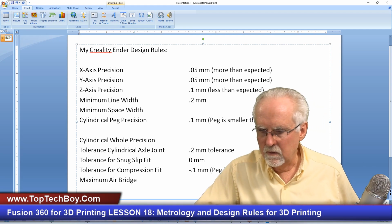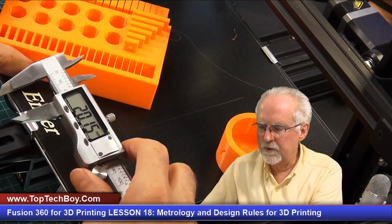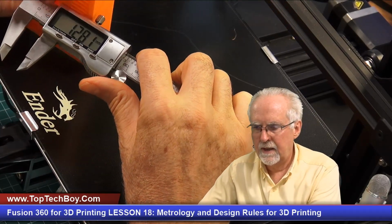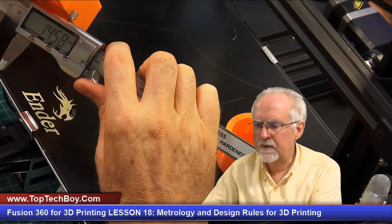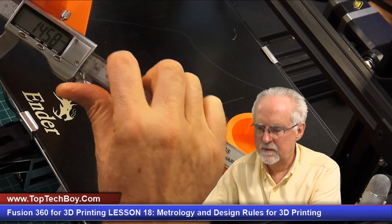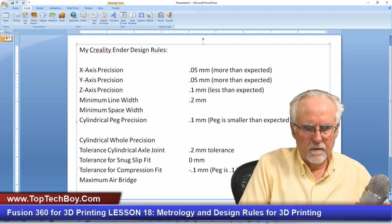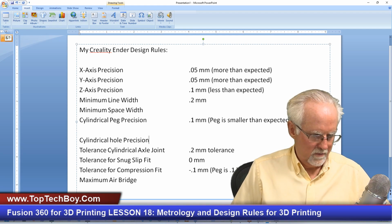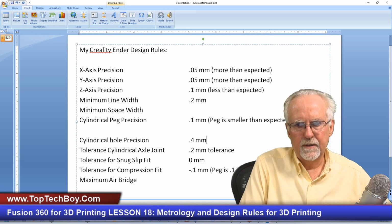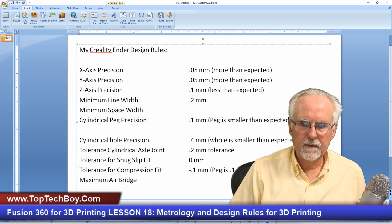Okay, now let's look at the hole, and we are going to come over here. And remember, it was this hole that was supposed to be 15 millimeters. So we'll come in and look at it. What we can see is that the hole is about 14.6. Hole is H-O-L-E, not W-H-O-L-E. So this is 0.4 millimeters. Hole is smaller than expected. Okay, the hole is smaller than expected.